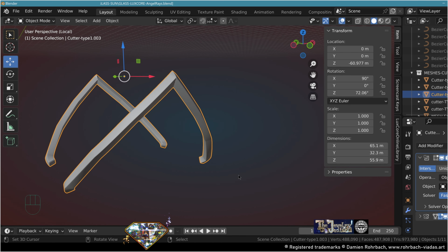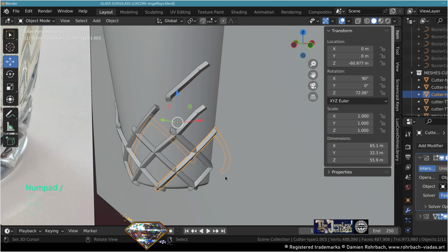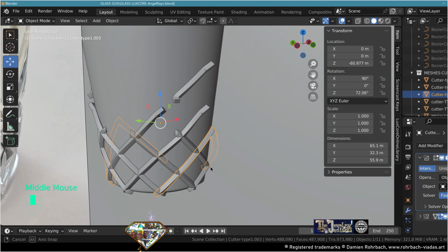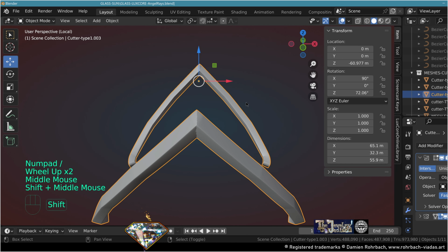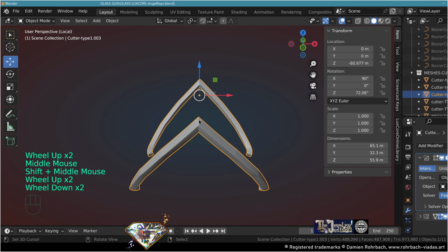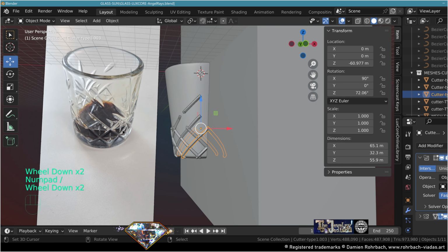Okay, and now the problem is corrected. So the filled caps, the caps are never connected to the rest of the mesh. That's something we all know. If you don't know it, you'll suffer endlessly. So this one is working perfectly. Now we can see that this intersection here is perfectly sharp, like in the design of the glass, okay?